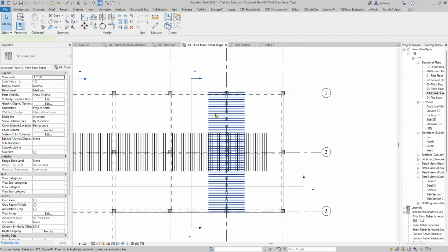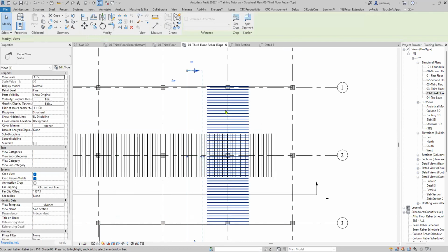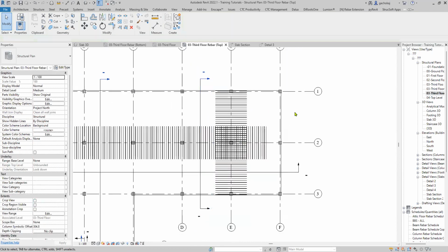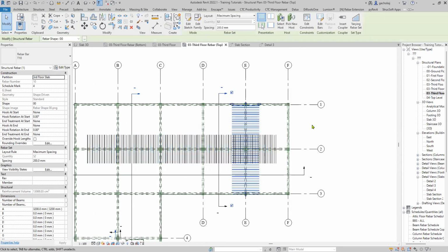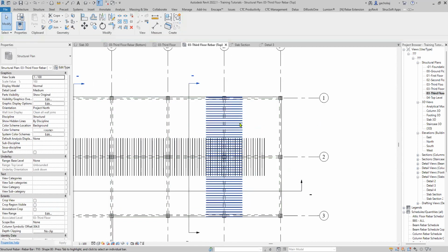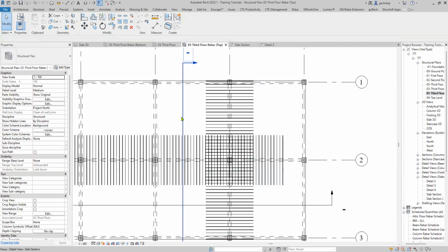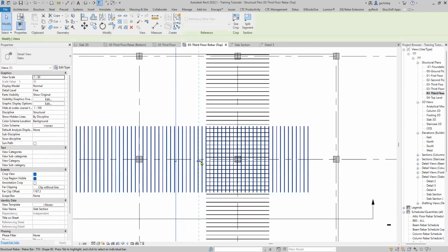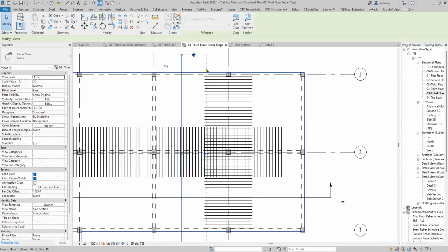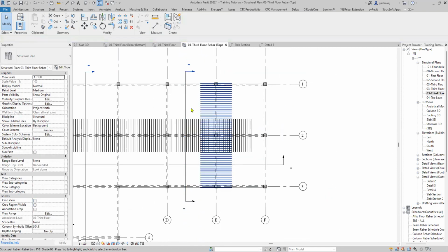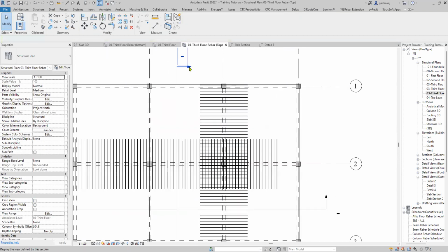There you have it. So I'll just check out the extents here, just like we did for these top ones. I'll do the same for these ones, adjust their extents. So I'll select these and maybe just edit the extents a bit so that I can see my top ones here instead of creating a new section completely.